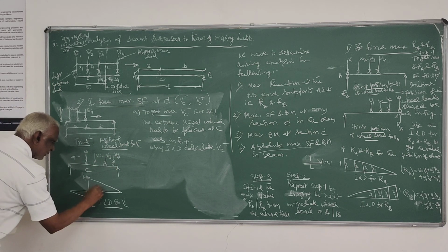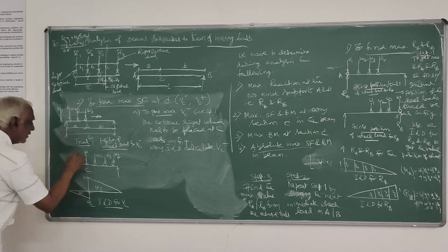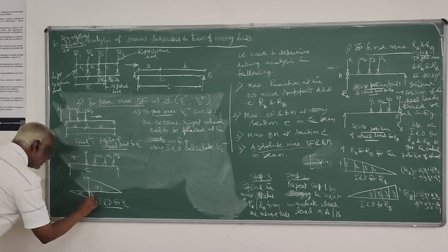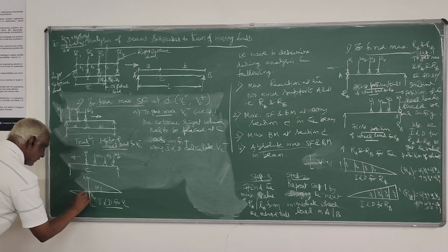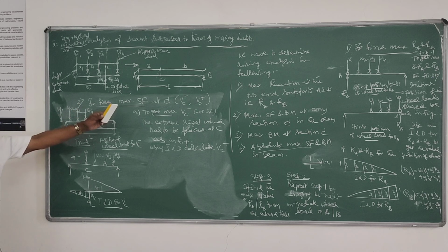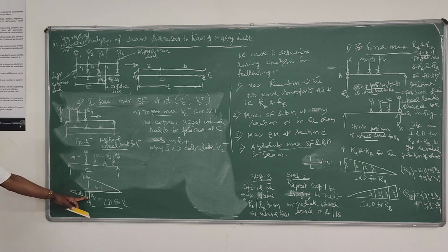This is positive shear, this is negative shear. For this particular position, you have to get the ordinate here, Y4, then Y3, Y2, Y1 for negative. Then you load now and calculate VC bar negative. Then you move the next wheel load to occupy, and calculate again.